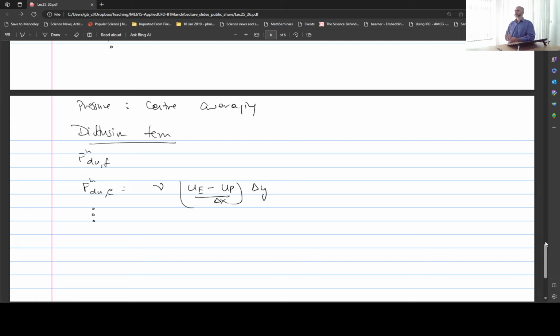But unstructured grids, on the other hand, are different. You may have seen those pictures of triangles and random elongated triangles and so on. Basically, you just put some nodal points and then you connect them through lines to make triangles in a 2D mesh; in 3D it becomes tetrahedrons. There are other kinds of meshes available as well. Unstructured means there is no structure as such. So you have to store the coordinates of each and every nodal point, and you have to store the information of connectivity between different points. So that means it's an unstructured mesh.